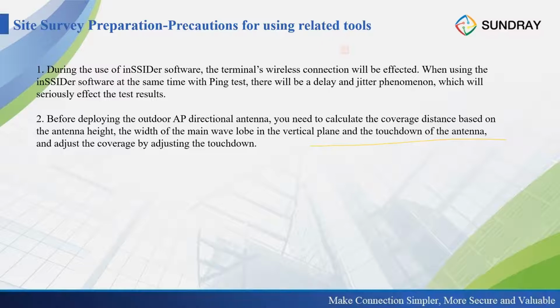Also, for an outdoor project, you need to know the antenna pattern and the beam. If the coverage is not good, you can adjust its downtilt, just adjust its direction, the angles of the APs. This one we usually do when we have an outdoor coverage project.